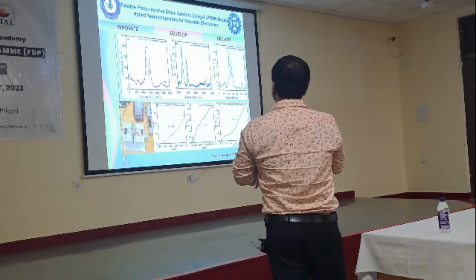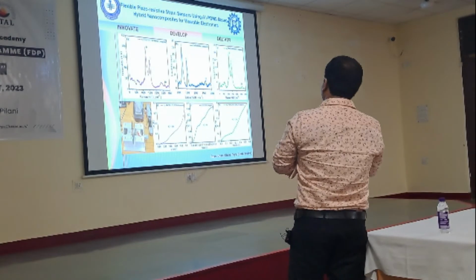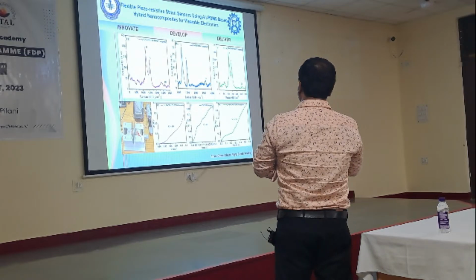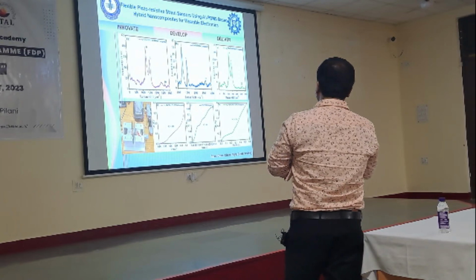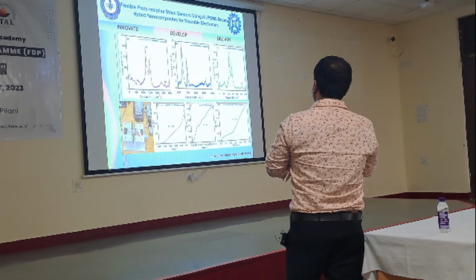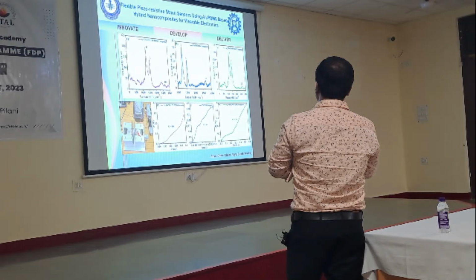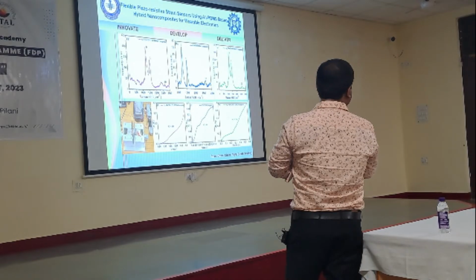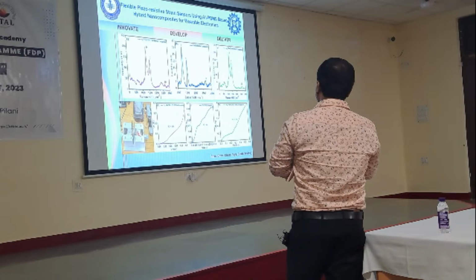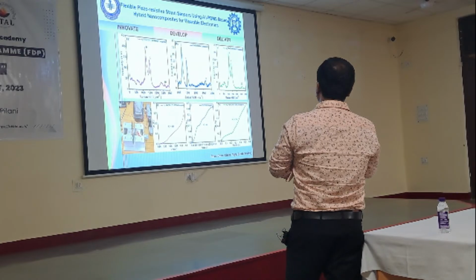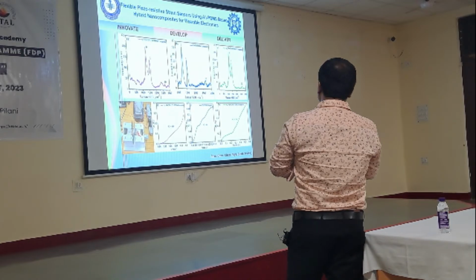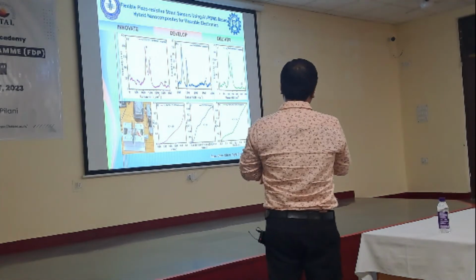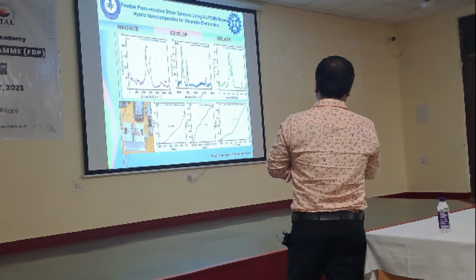And again here you see we have tested the device, where GF means gauge factor. This is the stage where tensile strain is applied from this to this, and your device relative resistance is changing, which is being determined. This gauge factor is actually the sensitivity. In this case 188, in this case this one and this one. So you can see from this plot the maximum gauge factor we obtained is 221. So this device is getting better results.